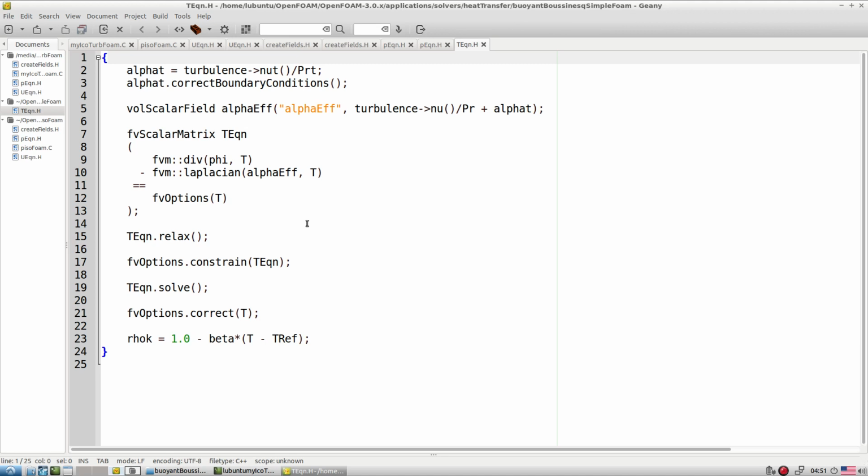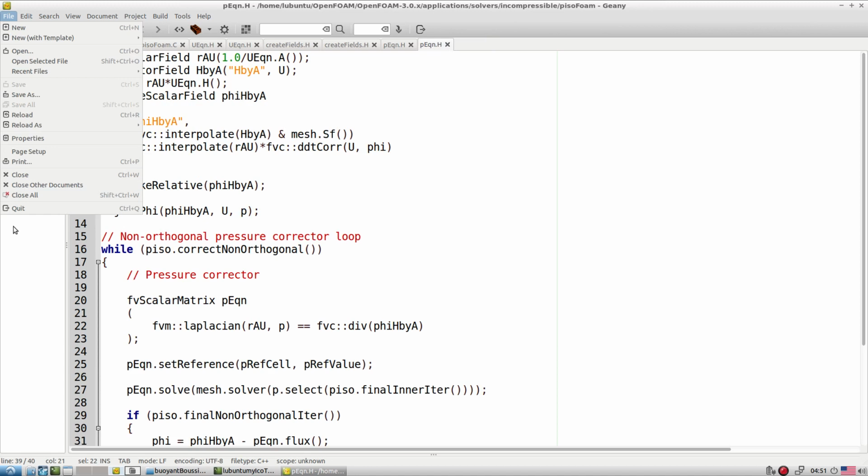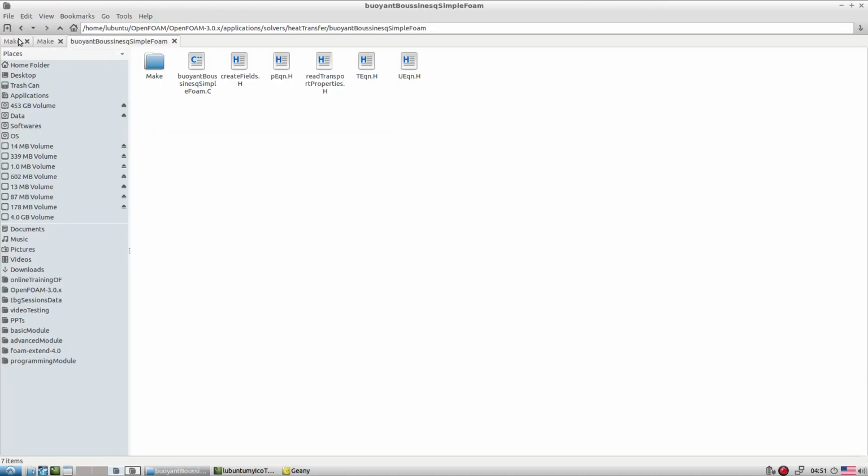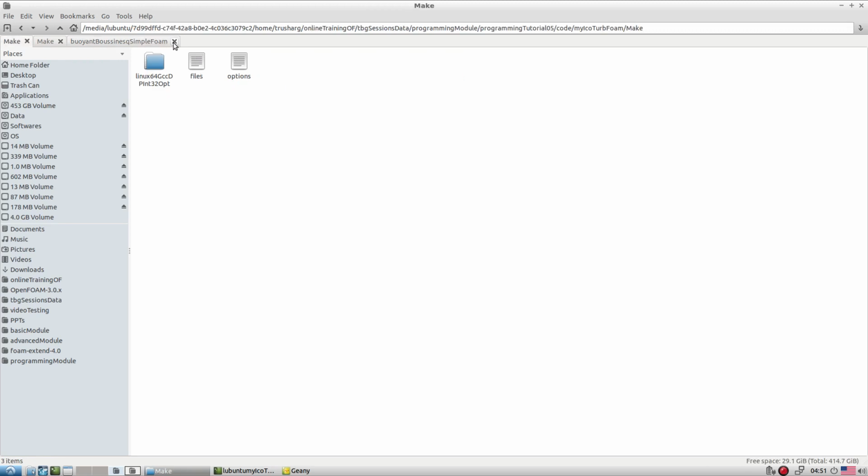So this is pretty good. Let's try to incorporate this T equation from here inside our developed solver. So we have an energy equation, the entire energy equation. If you want to incorporate it, how to proceed, let's understand that as well. Let me close this, but I want to develop an entirely new solver for that. So what I do, I add up, let's say, the pimple form. Inside the pimple form, let's incorporate this energy equation.